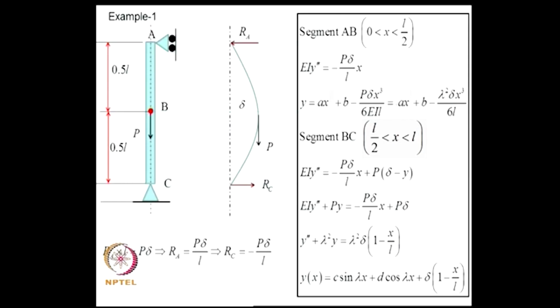So, what I am doing here will provide exact solutions within the scope of the beam theory that we are using. Suppose I have now a simply supported beam in which a load is applied at the mid span. Now, again I assume that a neighboring equilibrium state is possible, and I want to know at what value of P such an equilibrium state is possible.